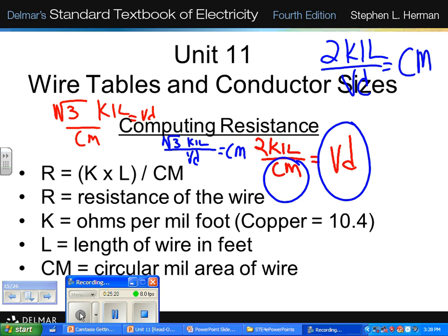Well, we can use that formula right here, 2 K I over the voltage drop that we want to allow, and since it's coming from a sub panel, we only want to allow 3% voltage drop, 3.6 volts drop between here and my little light, my little motor, right? But if we're going out, let's say 300 feet, how big a wire does it have to be now? Well, let's plug some numbers in here. Let me go to the next slide.